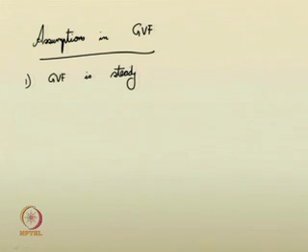Still, as it is varying with respect to space, it comes under the varied flow category, and the parameters are changing gradually, therefore it is gradually varied flow. So, gradually varied flow is a steady flow phenomenon. Mostly we consider the hydrostatic pressure distribution.